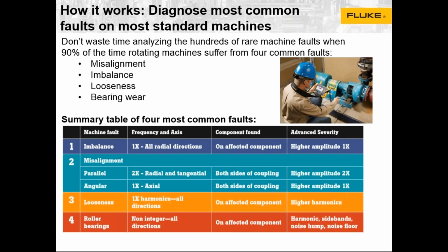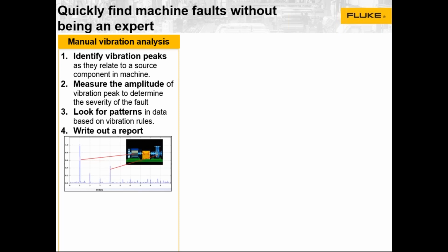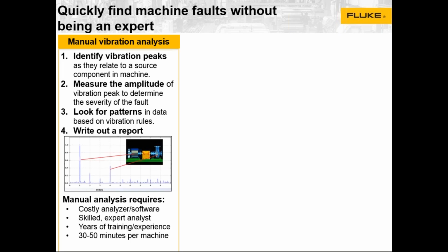We can use a tester, and in 10-15 minutes we can know whether there's any faults and to know what those faults are. And again, there's really 4 faults that we're looking for: imbalance, misalignment, looseness, and bearings. So there are 2 different ways that we could analyze data.